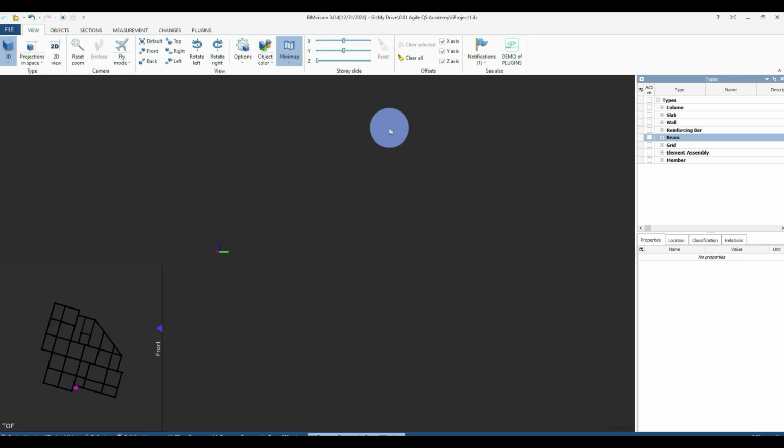We need first to view the model, understand the model, navigate through the model, then you can go ahead and extract. I don't recommend getting the model and starting to extract quantities without understanding its components, because you might find the model has different components. In BIM, you might find steel structures and concrete structures.